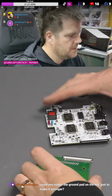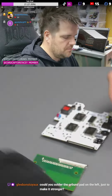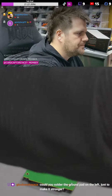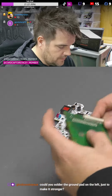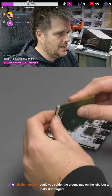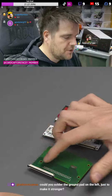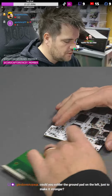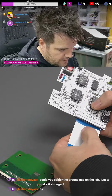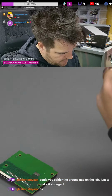There we go. Right, so now we can connect these two boards together. That's rock solid as well because there are that many pins on this, they're rock solid, they don't even need fixing. Funny enough, as I was saying that, you said, can I solder the ground plane? I can, but honestly, this is rock solid. I'm trying to bend it. You literally can't even bend it off the board. Because it's such a wide pitch and large connector, you literally don't even need to in this instance, but you normally would. That was my concern with this originally, was fixing it in with no mounting points, but it actually holds itself in perfectly fine.